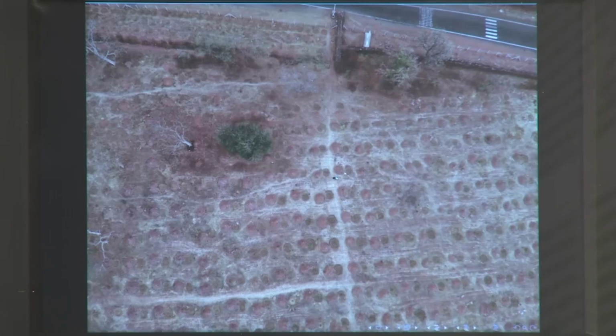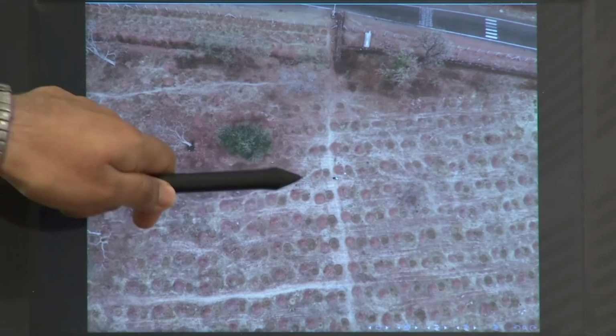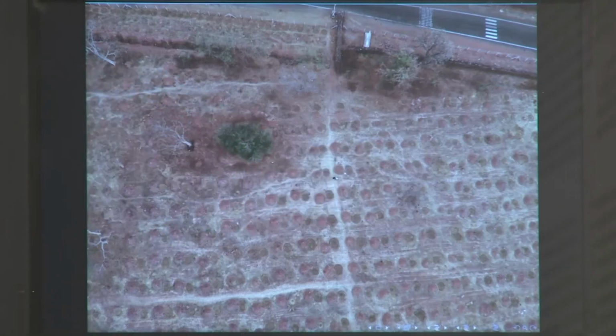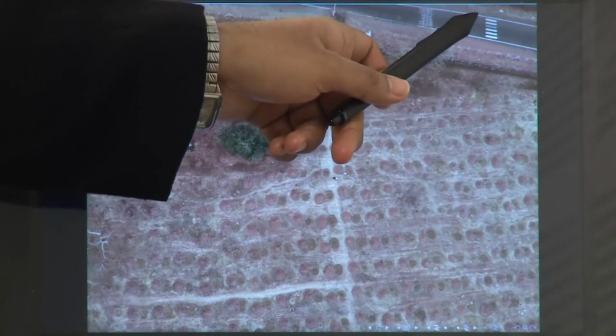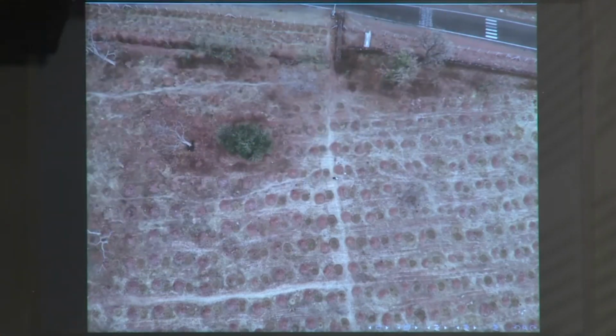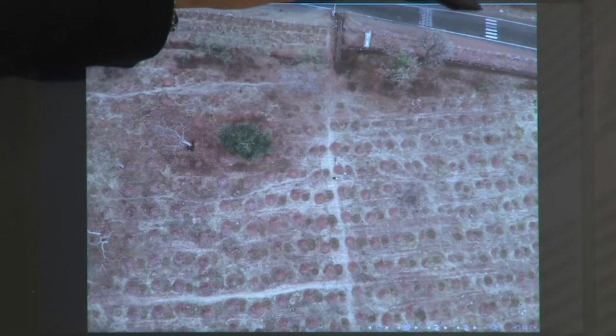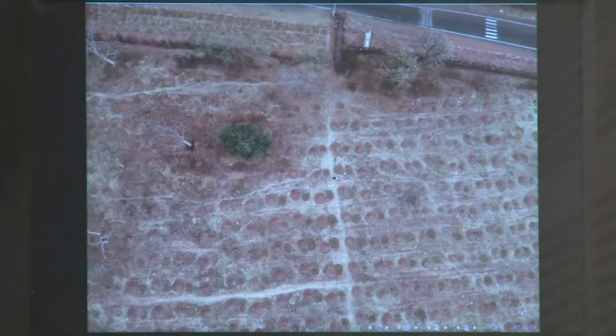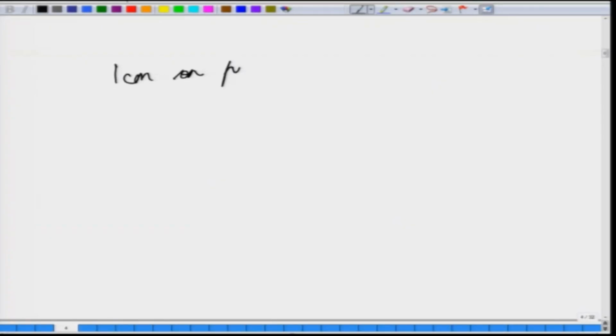So, when you have this photograph, you can directly take a scale, measure these distances, and then scale them up by using a standard distance. So, for instance, here you are seeing this road and you are having this zebra crossing, and in this case you can measure this distance on the ground, measure this distance on the photograph, and so you get a scale factor that in the case of your photograph 1 centimeter on the photograph is say equal to 8 meters on the ground. Now, once you have that scale, that 1 centimeter on photograph is equal to say 8 meters on ground.